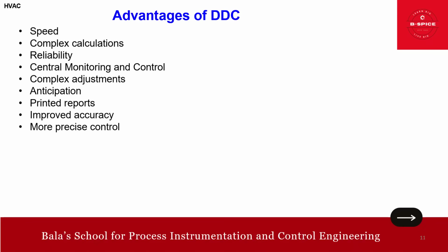Okay, then conservation of energy. Basically, it offers tighter control of the system. The hours of occupation can be refined and the temperature in the space remains at a more constant level. So that's about conservation. Second, sequencing. Sequencing provides a proper sequence of equipment startup after a system shutdown or a power failure. Then we have feedback. It not only sends control signals to the operating system, but also sends feedback and records data concerning the status, environmental conditions, and mechanical conditions.